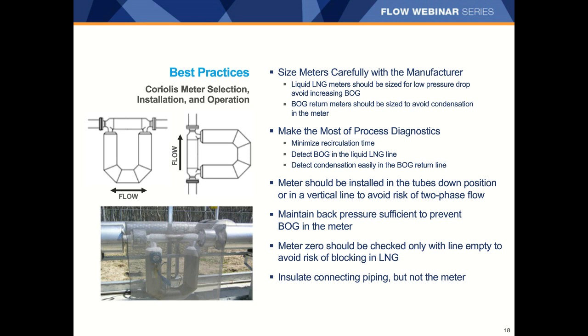Although you can choose to insulate the meter, we recommend you do not, because the case around the outside of the meter creates an insulating environment around the flow tubes, and where the LNG is passing through the rest of the meter, a good layer of ice will typically form that acts as sufficient insulation there. You can see an example of this in the photo.